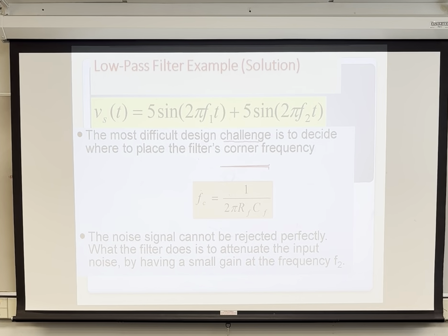Since it's 4 digits, if the first number is a 0, you're going to be less than a kilohertz. If the first number in your last 4 digits is 9, what's your frequency to start with? 9,000. And whatever comes after that. If your first number is 4, that's 4,000, so 4 kilohertz, and then whatever 3 numbers come after that. So you'll design with that frequency, and now you basically have to calculate R F and C sub F.